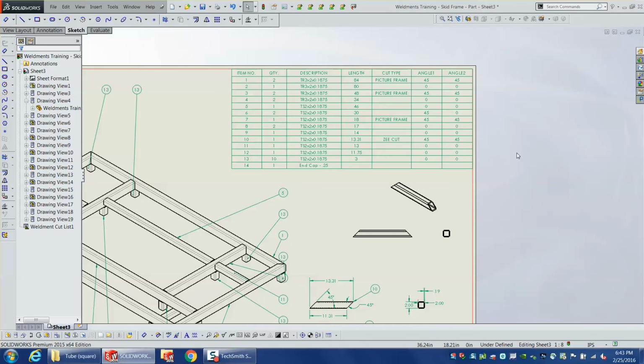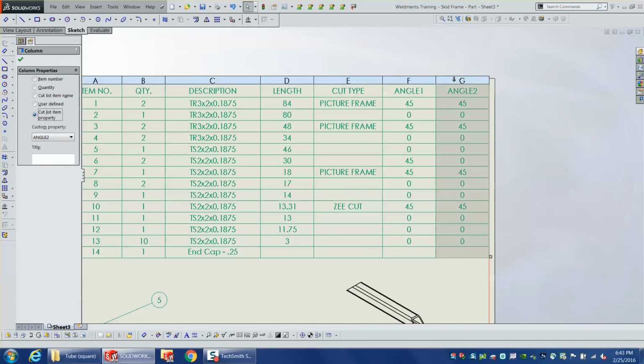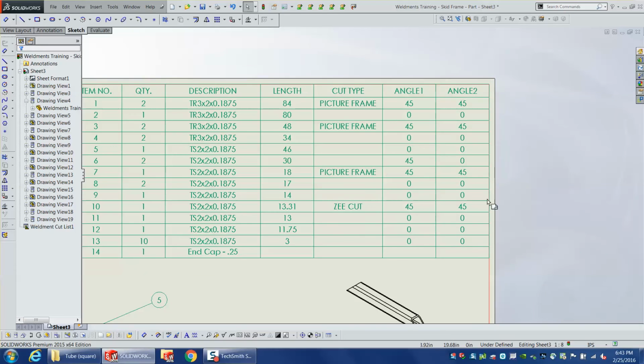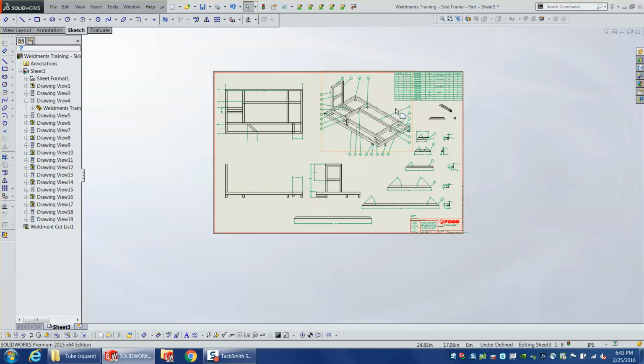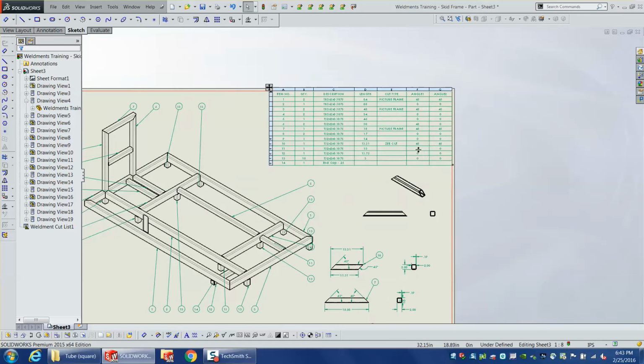Yeah, that's what I do now. And you can use a custom property added to your weldment cut list. But I still say the profile itself doesn't have a length until it gets used in a part. So if it had a length property of some kind, you wouldn't want that to be populated in itself. I understand why you want to show it in the same field, but